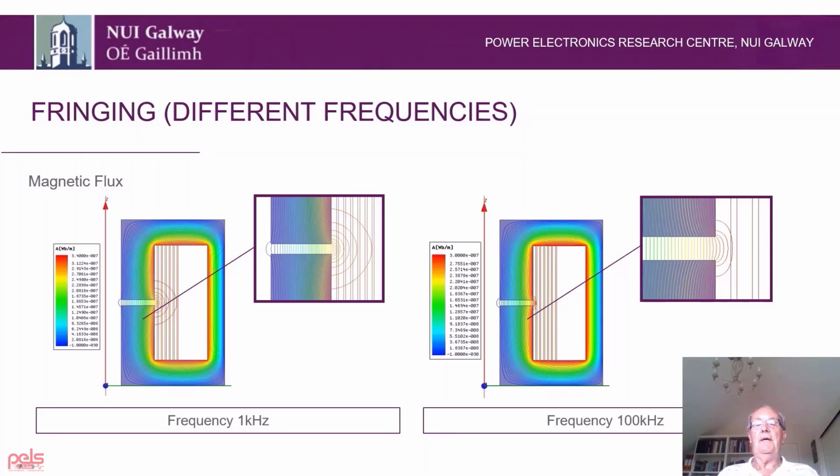Now, the last sort of losses I want to deal with are fringing effects. This arises now in modern power supplies where you have, say, an LLC resonant converter, where you've 2 inductors and 1 capacitor, and you have a resonance between the inductance and the capacitance. And in order to create one of the L's, we usually have a gap in the transformer.